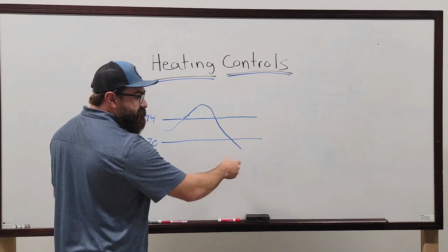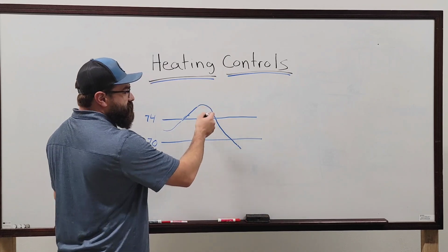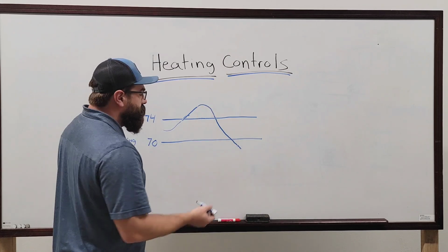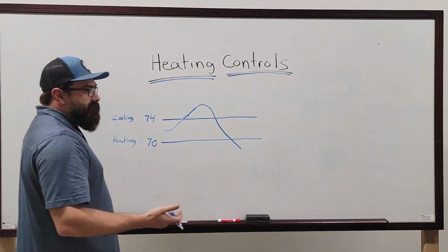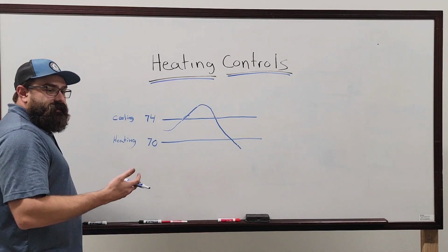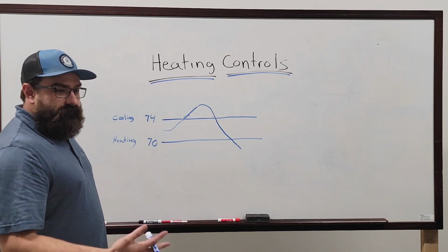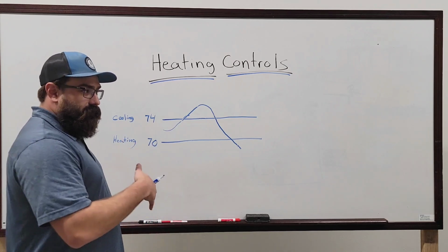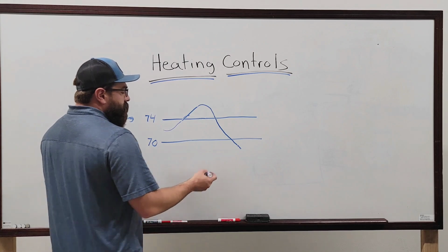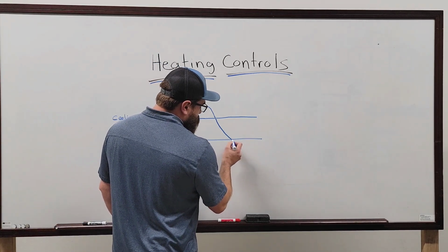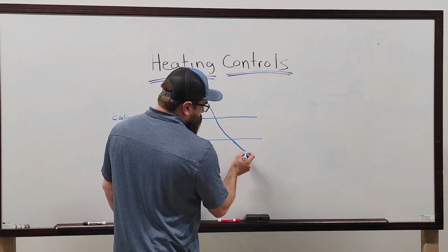As temperature decreases, your output increases. In cooling, as temperature increases, your output increases. So it's like reverse acting thermostats versus direct acting thermostats, right? Reverse acting is heating, direct acting is cooling. So yeah, just to touch on that.